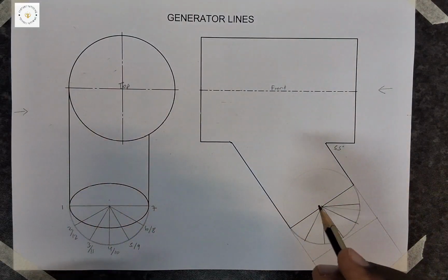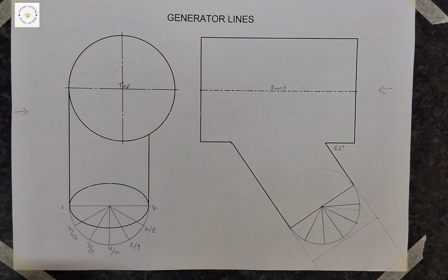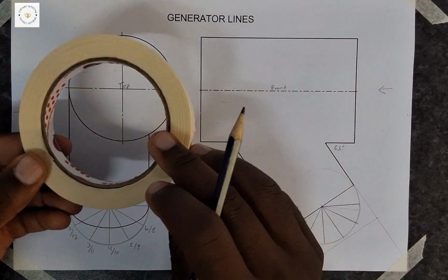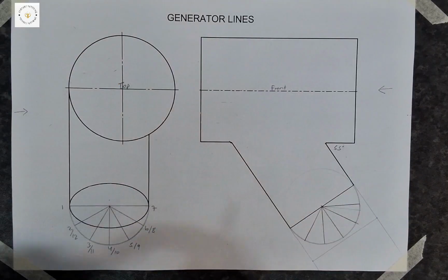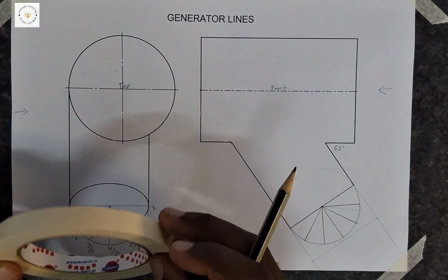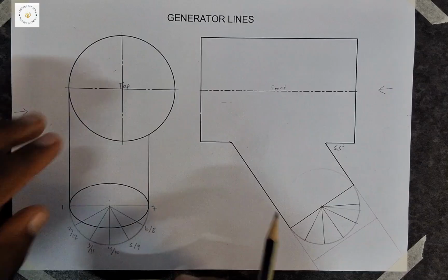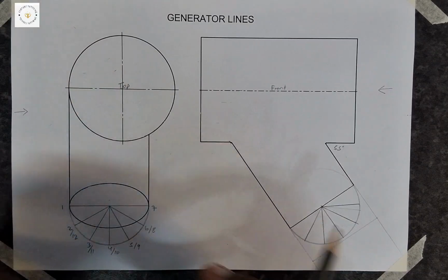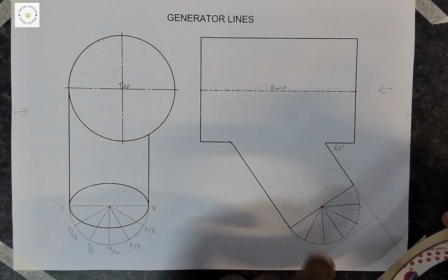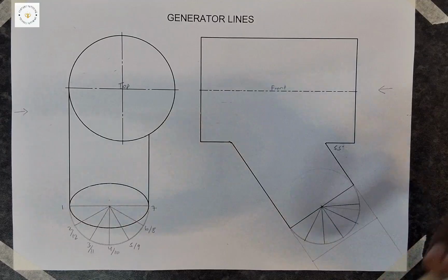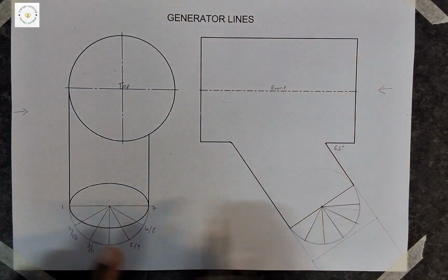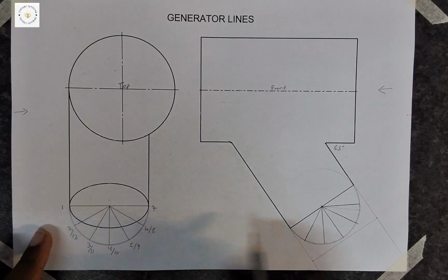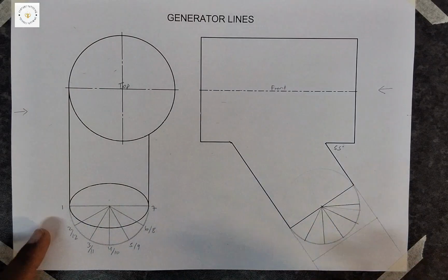Now what happens is that, as I showed you, when you're rotating from top view to front view, you're rotating it 90 degrees. Your circle or semicircle here, when you're looking at the top view, is going to be different when you put it on the front view. So it's quite different. It's quite important that you really recognize that, because you can't just transfer the numbers as they are. This won't really be here, right? So how do you do it?